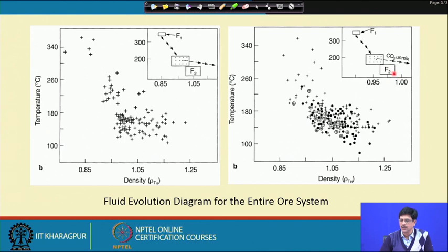So, the remaining aqueous component would have an apparent increase in its salinity, just as it happens in the case of boiling, when the vapor phase gets separated out of it. Because of the negligible solubility of the electrolytes in the vapor, the residual liquid gets apparently higher in its concentration of total dissolved solids, and there is an increase in salinity in a boiling condition.